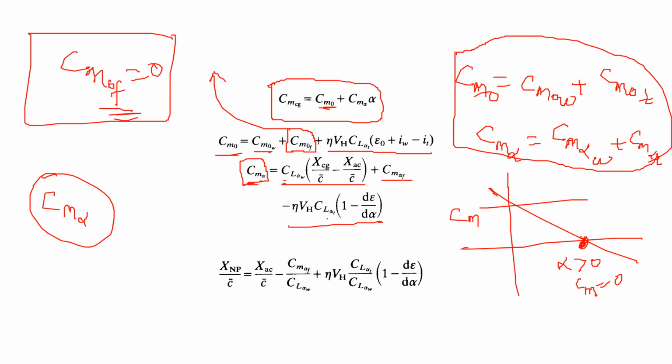your aircraft becomes neutrally stable. It cannot naturally stabilize itself. You have to pull the controls. That situation happens, and beyond that, it's just unstable. It's bad. You pitch it positively, and then it'll simply go to the 90-degree pitch angle and just do crazy things. You don't want that. So you want CM alpha to go maximum to 0. It's always negative, but it goes towards 0 when CG changes.